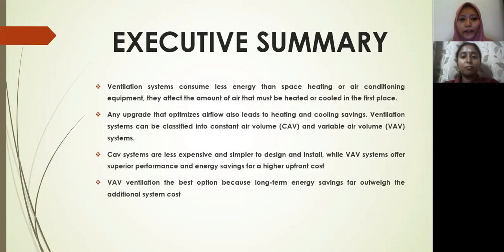They affect the amount of air that must be heated or cooled in the first place. Any upgrade that optimizes airflow also leads to heating and cooling savings. Ventilation systems can be classified into constant air volume and variable air volume systems. CAV systems are less expensive and simpler to design and install, while VAV systems offer superior performance and energy savings for a higher upfront cost.